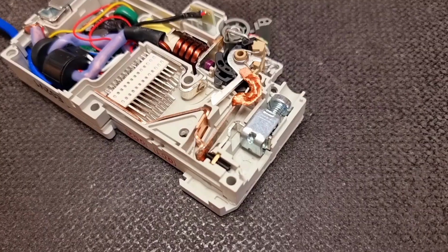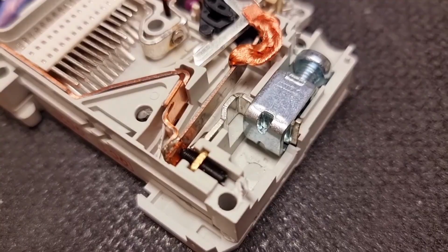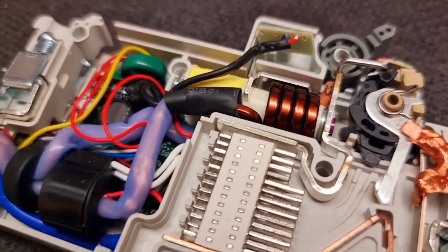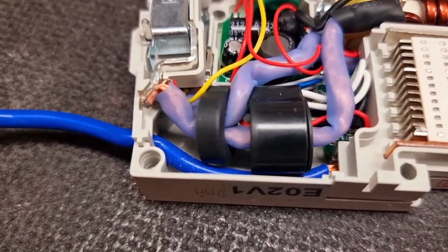So you can imagine that this is slightly more technologically advanced than a simple fuse, MCB or RCD protection. However, it is very reassuring when you look inside the AFDD and see that all those components still remain. You can see the bimetallic strip here and the electromagnetic coil that takes care of the overcurrent protection, and then the current transformer that helps when using an RCD for additional protection. So that helps us to understand that when installing a single module AFDD, it's not just providing protection against arc faults, it's also providing overcurrent and RCD protection.